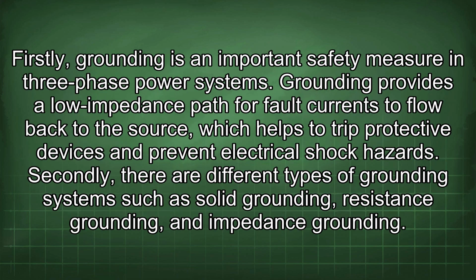Firstly, grounding is an important safety measure in three-phase power systems. Grounding provides a low impedance path for fault currents to flow back to the source, which helps to trip protective devices and prevent electrical shock hazards.